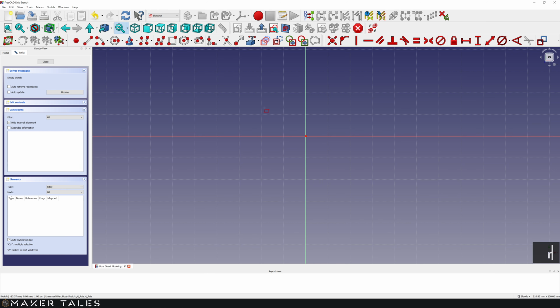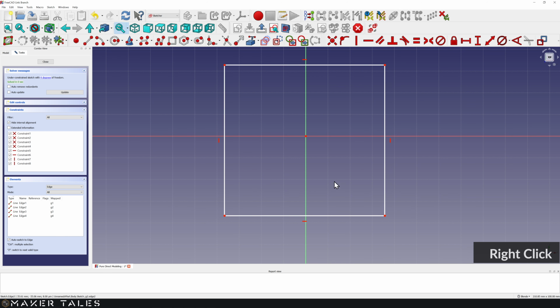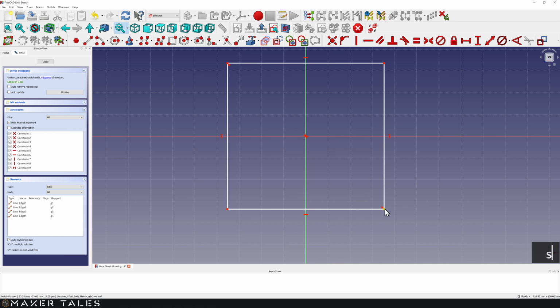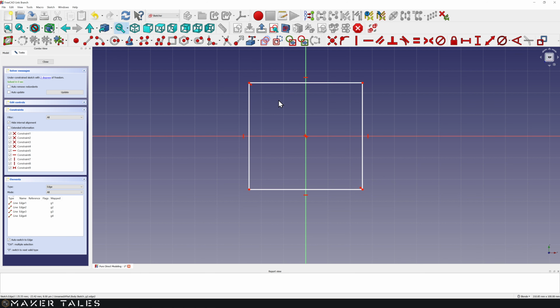So we'll press R, create ourselves a rectangle here, and the entirety of my whole design is going to be centrally locked. So the main root origin of all my design is going to be center-based, which means I'm going to select these two here, this origin point in the middle, press S and create a symmetry lock. So straight away, FreeCAD knows where this is in the 3D environment, and it has the bonus that this locks down quite a few degrees of freedom.